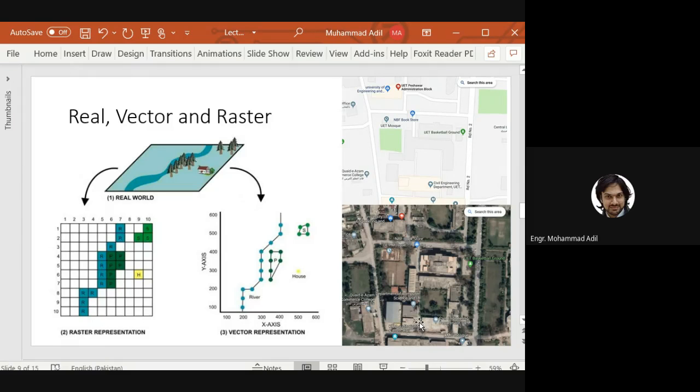If you go there in reality, turn on your mobile phone GPS device, get your coordinates and write them on here, and go to this corner of this road as well, which is easily identifiable on the ground there. Turn on your GPS and get the coordinates from there as well. So these 2 points are now known. You just put them on the map, then these are enough.